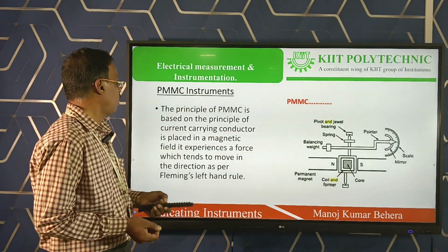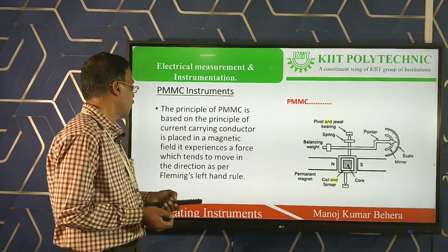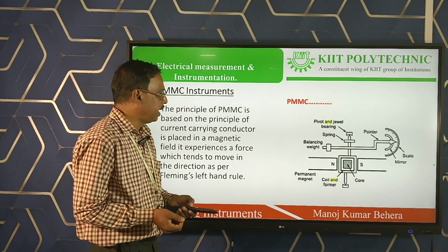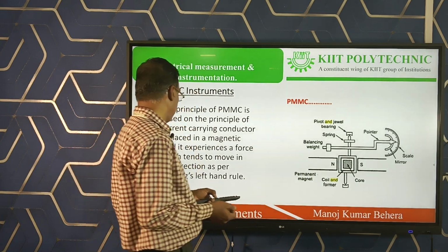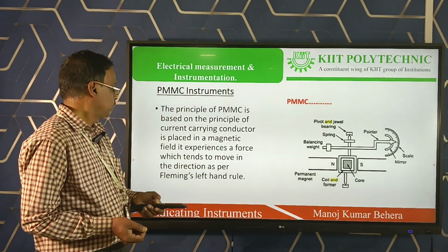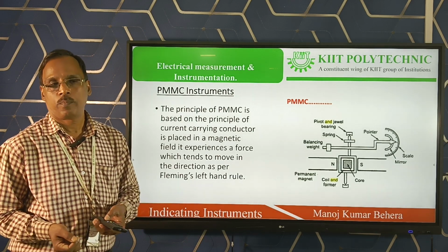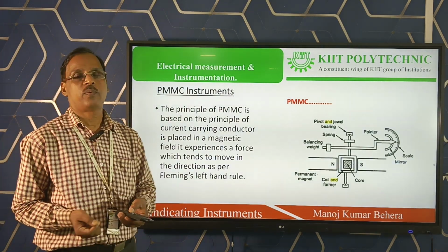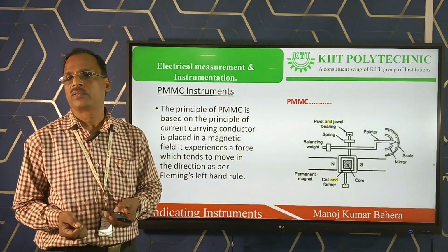What is the basic principle of PMMC instrument? Whenever a current carrying conductor is placed inside a magnetic field, that conductor experiences one force. The direction of the force is defined by Fleming's left hand rule.